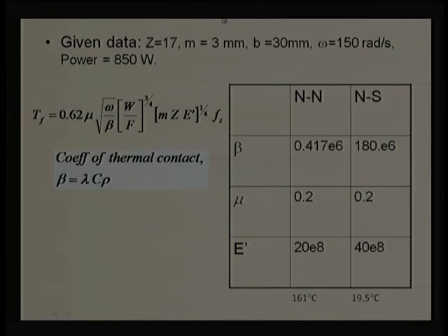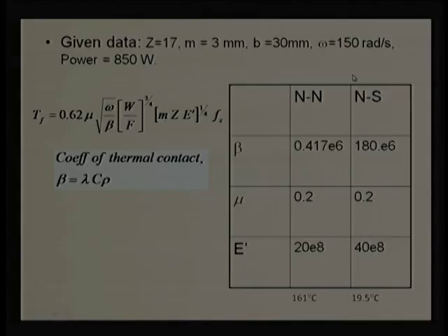We say that whenever we choose gears, maybe one polymer gear, the other should be a solid material gear which has very good hardness and also high thermal conductivity. If the gear has hardness and thermal conductivity, surely we can use this kind of pair, one polymer gear or pinion, and the other as steel or some material which has a high thermal conductivity. That will be preferable compared to this kind of thing.